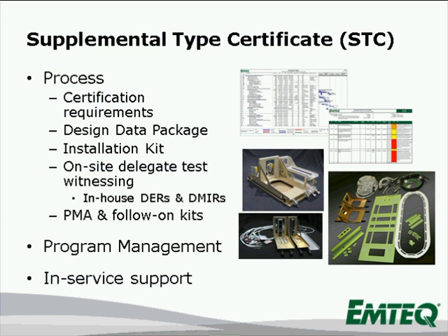So with the supplemental type certificate, one of the first steps that's determined is what certification requirements there are. So where the customer is operating the aircraft, where the aircraft is registered, whether it needs an FAA STC or an EASA STC or both, and possibly a validation in a foreign country.